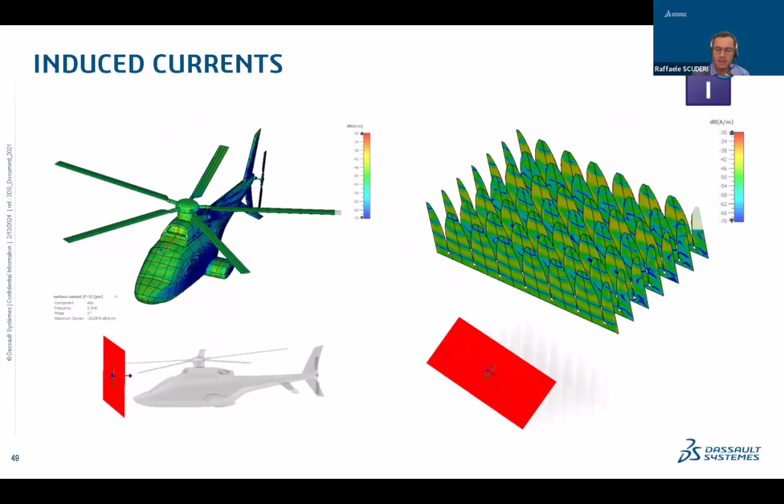And we have been already pretty meticulous on studying locally our targets: hotspot, ISAR, range profile, rays, etc. Induced currents are particularly suitable when we use the integral solver. Why? Because it natively calculates current. So the currents are the basis, let me say, for us to calculate then the scattered field. So let's study the currents and let's have a look at them and see if we see something strange, if we can understand something.